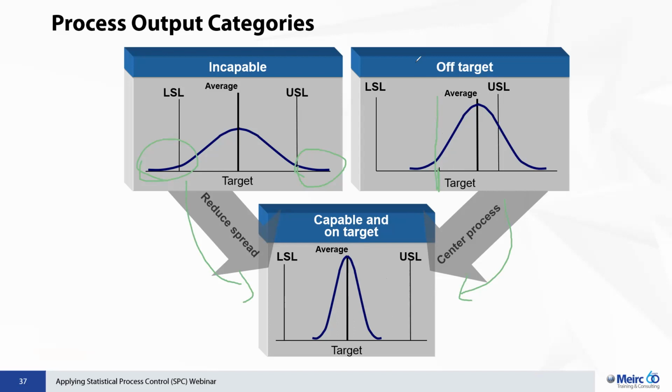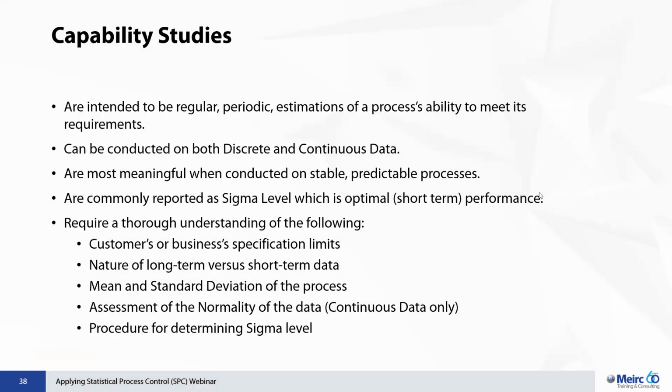And this is where I can come in and then calculate some numbers for these capability studies. So the most famous capability studies they refer to as the CP or CPK. Now I'm going to ignore CP because it has a drawback that it doesn't consider the centering of processes, something let's not discuss.